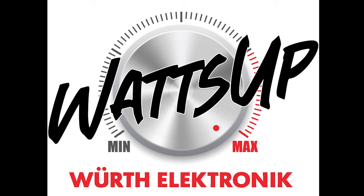Our sixth tip is about the advantages and the disadvantages of magnetically shielded inductors. Now, one of the advantages of magnetically shielding the inductor of the same type is that the higher inductance value means lower DC resistances for the same inductance, which equals lower wire losses. The disadvantage of magnetically shielded inductors of the same type is that we only get slightly increased core losses due to a larger core volume. Given correct dimensioning, the core losses remain lower.